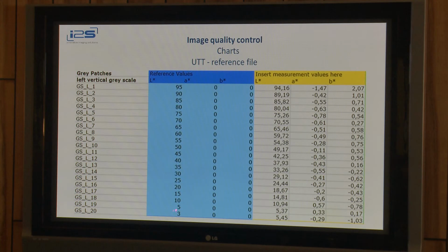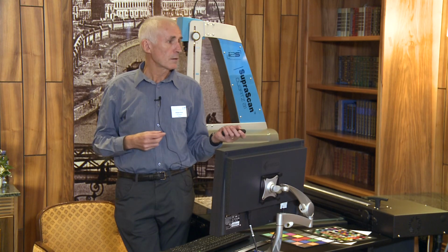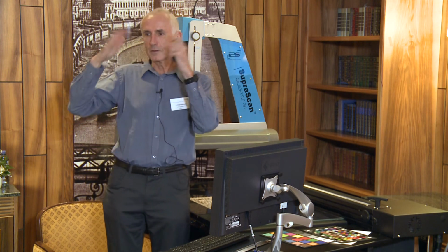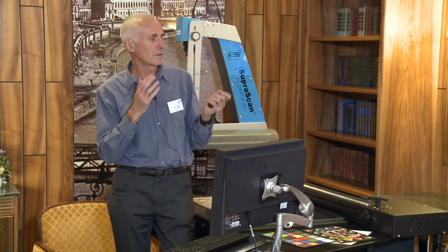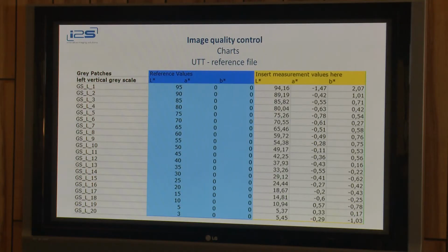And if you look down, the last patch was supposed to be L3, and in fact it is sometimes higher than the other one. And this can make big problem when you check the gain modulation, which is the slope between two patches. If they have the same level, in the formula you divide by 0, so you can get anything. So now we don't check this one anymore.